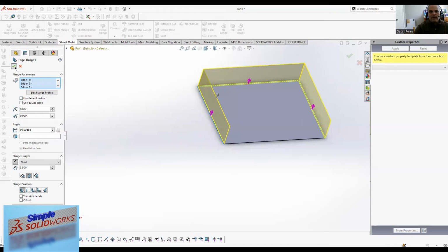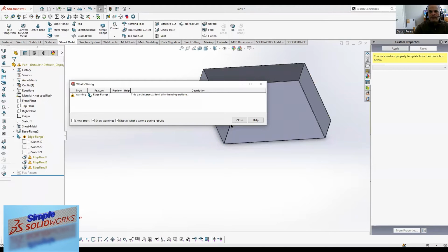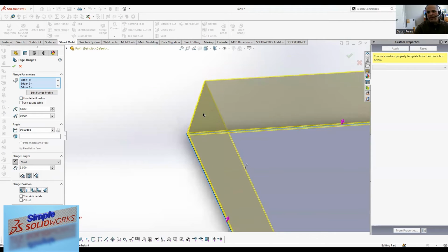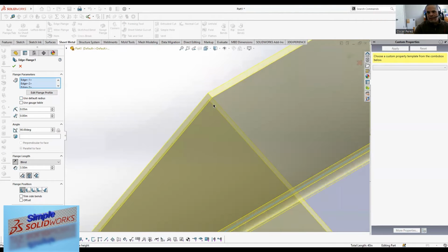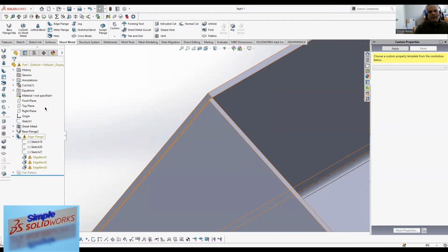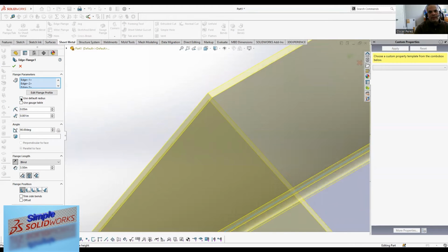So, oh, it's happening because again, it doesn't have the gap distance, right? It doesn't have that gap distance. So if you want to fix that, you're going to have to give it a gap distance of 0.001, something like that. Okay. Let's try that again.